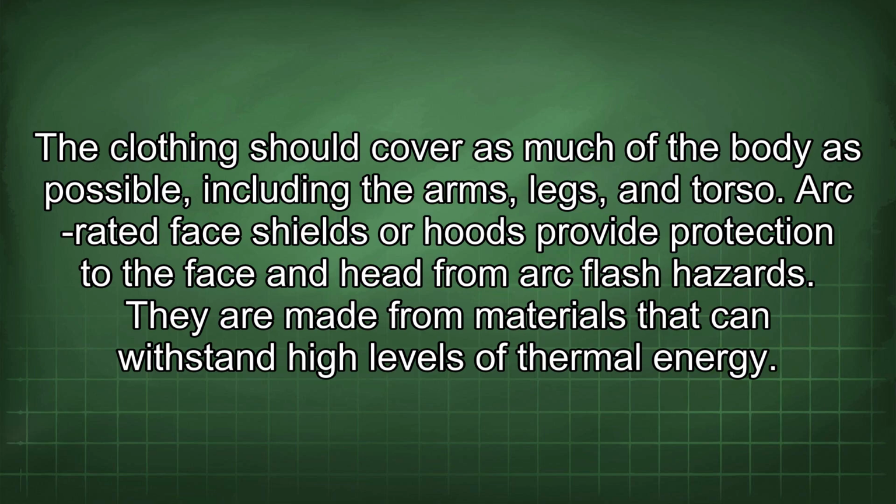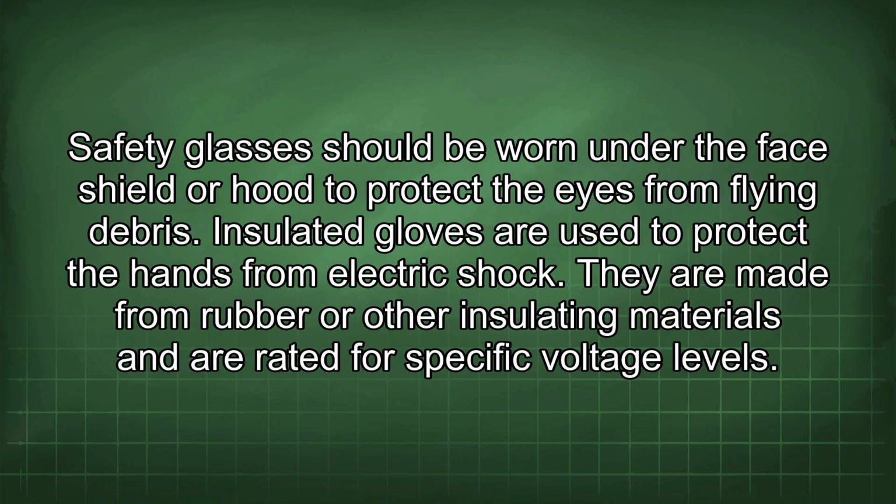Arc-rated face shields or hoods provide protection to the face and head from arc flash hazards. They are made from materials that can withstand high levels of thermal energy. Safety glasses should be worn under the face shield or hood to protect the eyes from flying debris.